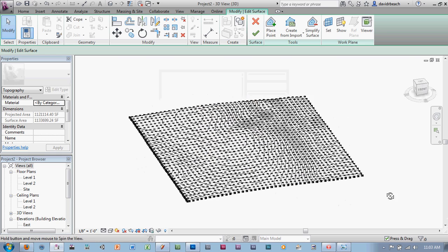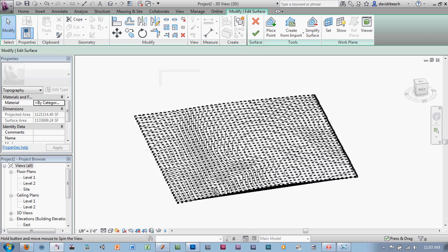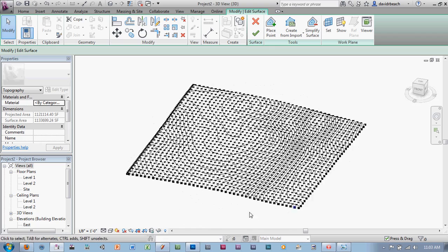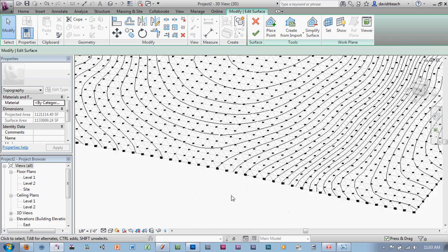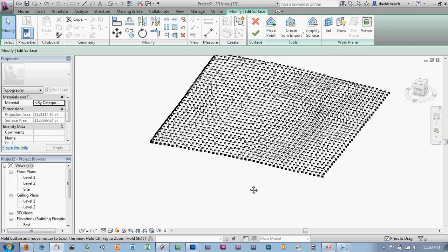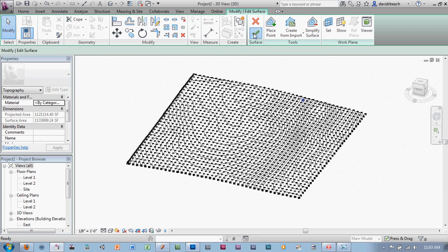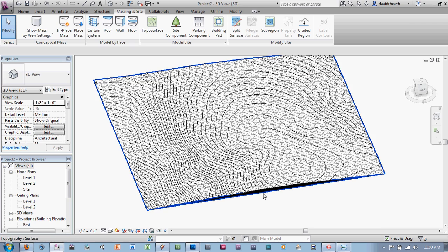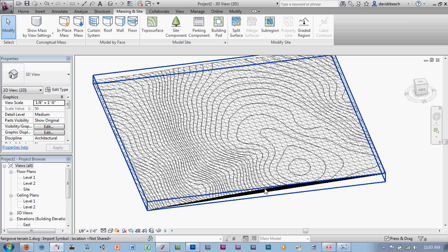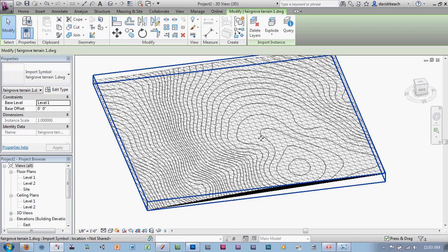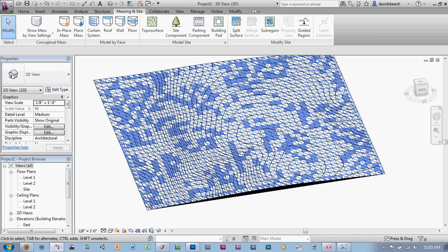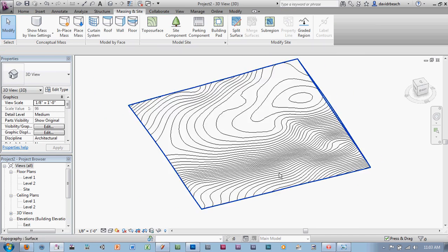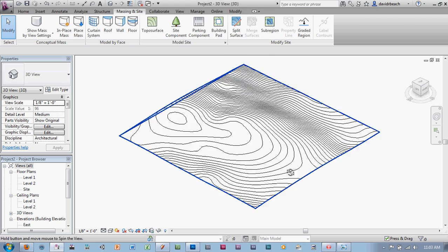And you'll notice this immediately builds a workable topography map inside of Revit. You can see the topo lines, everything that's been generated. So I'm going to click the green check for OK to accept the values. The next thing that I want to do is I actually want to delete that original AutoCAD file. So I'm going to use my Shift key to make sure I'm selecting the DWG. I'm going to delete it, and so all I'm left with now is the topo map.